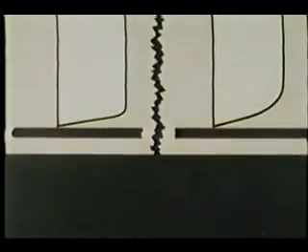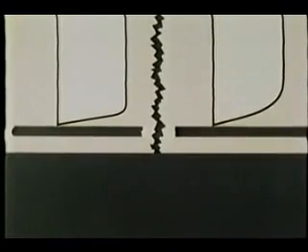Because there is no vorticity upstream of the plate, and because the circulation per unit length along it is constant, we conclude that all of the vorticity is generated in its length. Upstream, 95% of the total vorticity is contained within this area. Downstream, 95% of the total vorticity is contained within this area. Viscosity acts through the mechanism of molecular diffusion to spread out the vorticity as it is convected downstream. The local boundary layer thickness is a measure of the distance vorticity has diffused away from the plate.